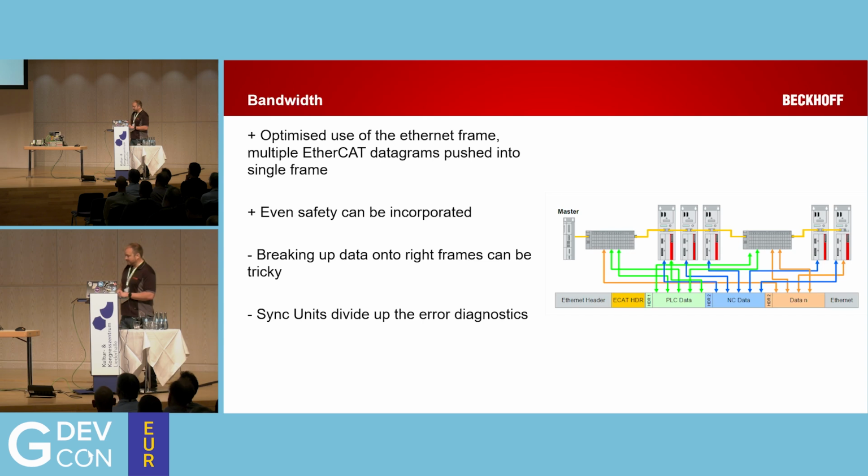Building a big EtherCAT network, which in principle is only limited to 65,000 devices, is a problem. Because once you get to that sort of size, you're talking a lot of data that needs to then be broken up into different frames in order to not overload your networks. So 65,000 devices guarantees a lot of data. Now, with a lot of machines, EtherCAT has absolutely no issue with this, but when you want to cycle at different rates, you then break up into different frames.